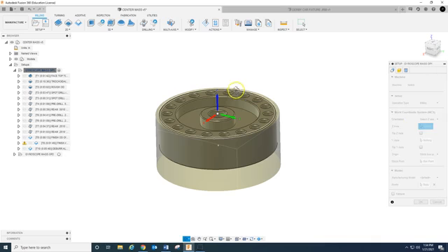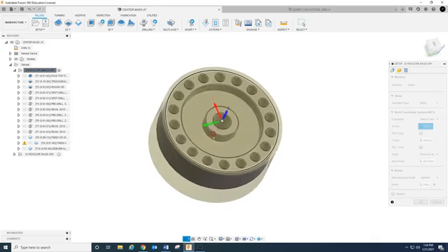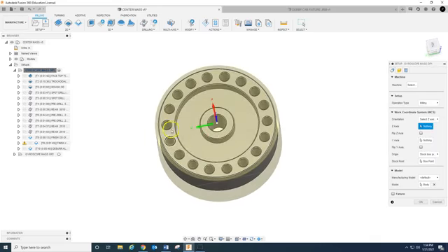This is where you tell it the orientation, like where do you want your G54 set? So for a rotative type part like this, it makes all the sense in the world to do G54 in the center. That's where everything's based off of anyway, so it just makes sense. So this is where we select all that.